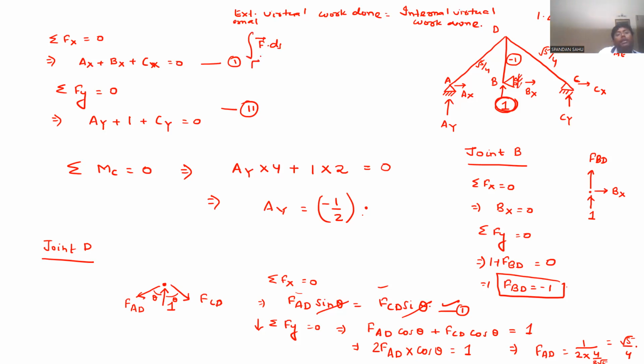Now, in this case, when you are applying this 1 unit load, was it initially present there or not? Sir, it was not present. It was virtual, you are applying it. Yes, sir. So this is the virtual load. But under this virtual load, once you have applied it, the displacement corresponding to that will be real. You can visualize really that when you are applying that 1 unit load, there will be corresponding real displacement occurring in the structure.